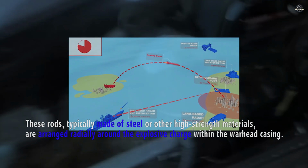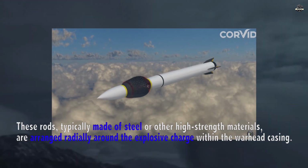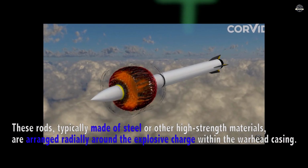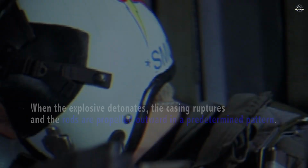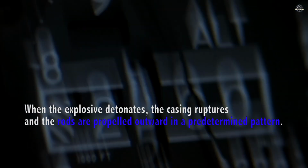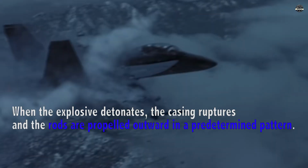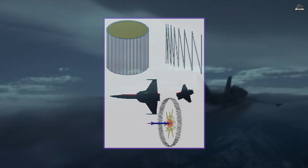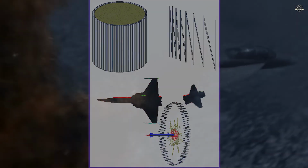These rods, typically made of steel or other high-strength materials, are arranged radially around the explosive charge within the warhead casing. When the explosive detonates, the casing ruptures and the rods are propelled outward in a predetermined pattern. This results in a cone-shaped blast wave with a high velocity and kinetic energy capable of penetrating and shredding the target.